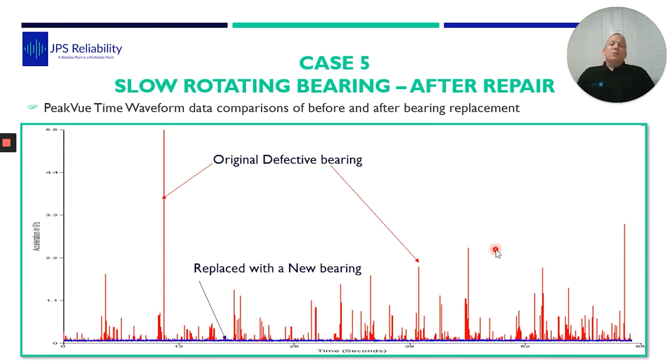One thing we did notice on the bearing, which we thought was quite a cause of failure, is that on the first image you saw the grease pipe coming in and lots of grease coming out. The bearing's about that diameter. There's only one input for the bearing for grease. Even though there's a few holes around it you could pipe around, they were putting the grease into one point.